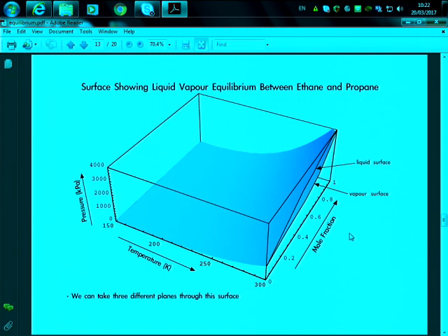So if I want to have a maximum liquid, or if I want to get methanol from the mixture. Yes, liquid phase. If you want to get methanol only from the mixture, let's say. So if I want to have 100% of methanol from the mixture, you could end up around this point, where this will be the vapor. In the vapor you will have 96%, and then in the liquid you will have that amount. So you will end up with these two points in the liquid and in the vapor phase. So in your situation, 100% is impossible.